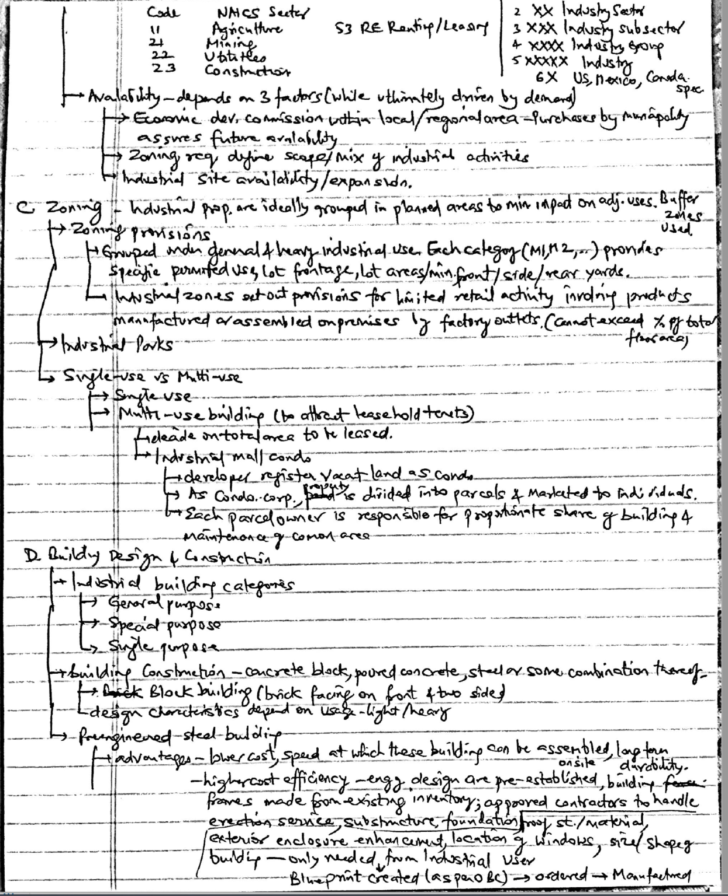being very common. The built-up roof consists of asphalt, felt and gravel. Successive layers of felt and asphalt are layered over the entire roof. The final coat of asphalt is then covered with granular base layers of metal aggregate.